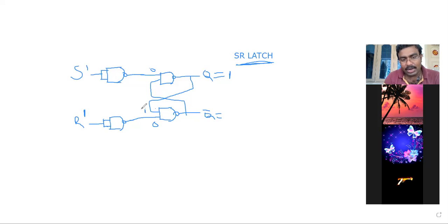Guys, tell me, if 1 and 0 are your inputs, what will be your output? 1 here. That one will be reaching here. Guys, again tell me, if 0 and 1 are passing through the NAND gate, what will you get? 1 here. So, guys, you observe one thing. What is happening here? What is the value of Q you got now? 1, sir.